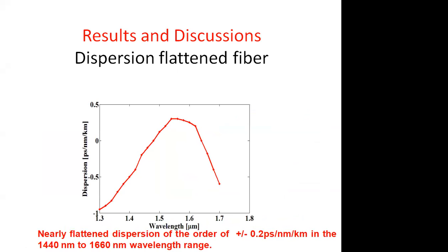And there are some applications in which we are using a wavelength of 1550. But we are not only using 1550, we are using a window, and at 1550 we have less dispersion. Above 1550 and below 1550 we have dispersion. But we need to design a fiber wherein we have a flattened dispersion over a band.